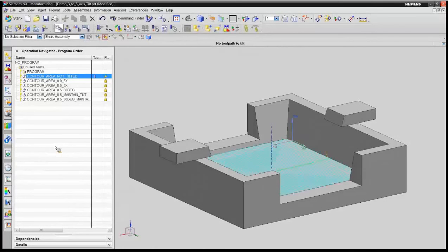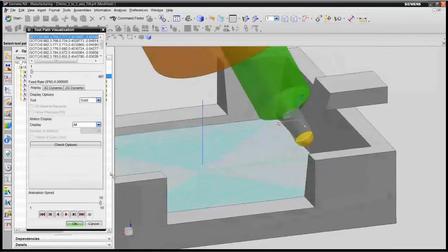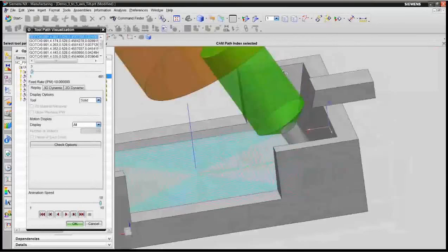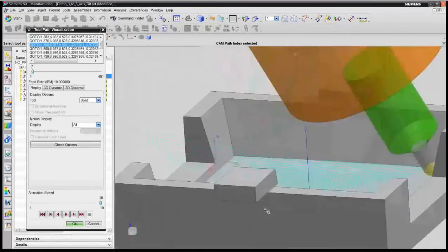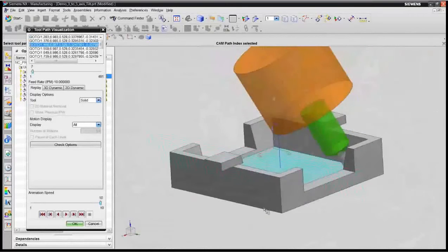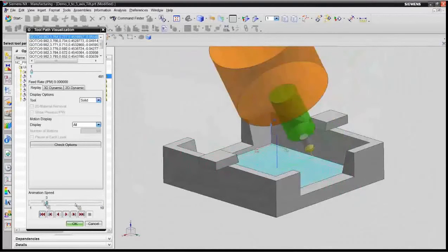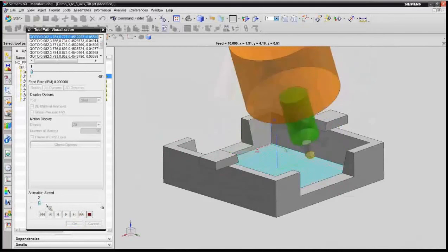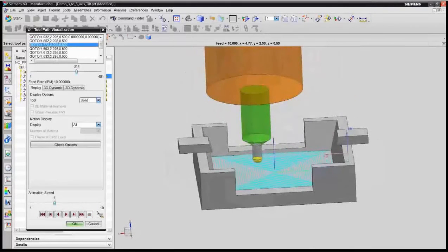This toolpath that was already created, that quickly, I now have a 5-axis toolpath. And if you notice, we are now tilted enough to clear the clamps, so the holder is not colliding with the clamps. And as we get over here into the corners, it's tilting both directions away from the part also. Let me slow this down a bit. Let's let it run through just a little bit. What I want to do is let it go just enough that you can see, once it gets out into the part, it stood back up.